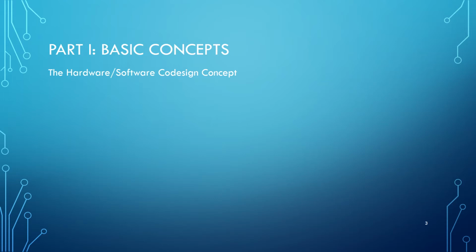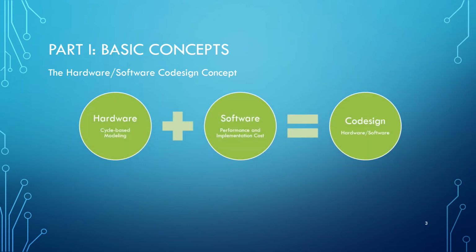The single clock synchronous model cannot express every possible hardware circuit. For example, it cannot model events at a time resolution smaller than a clock cycle. Thus, some hardware cannot be captured using the single synchronous model, for example, asynchronous hardware and dynamic logic.